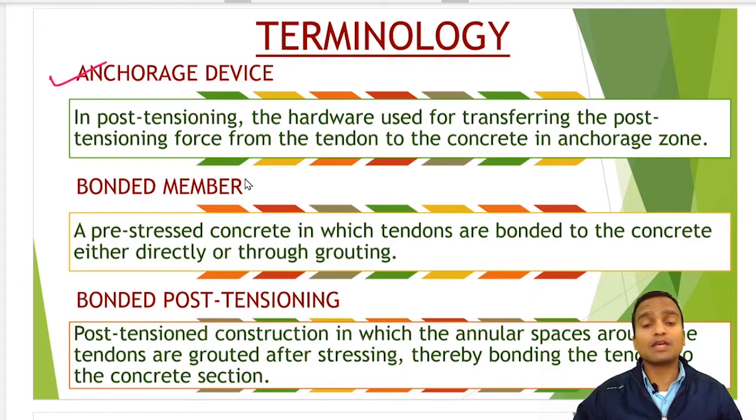When we have stretched the tendons, they will remain stretched as long as we have installed the anchorage devices on the prestressed concrete, and these anchorage devices will compress the concrete in the anchorage zone. So the entire concrete in the anchorage zone will be prestressed.